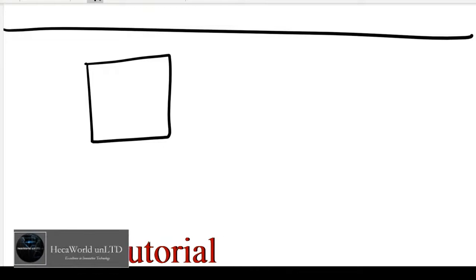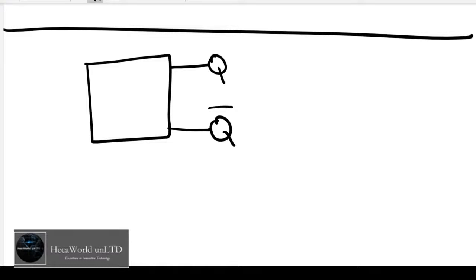One of them we're going to look at quickly is the JK flip-flop. It's much like other flip-flops, but almost all flip-flops have a Q, which is just your regular output, and a not Q, which is the opposite of Q. Then you have the J input, the K input, and then you have the clock.